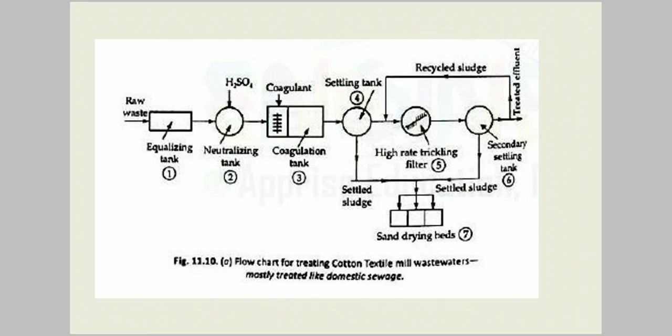In order to produce water of uniform characteristics, we mix the water from all the steps of processing in a single tank. We allow it to stand by for some hours, and we mix the water so as to produce uniform characteristics.